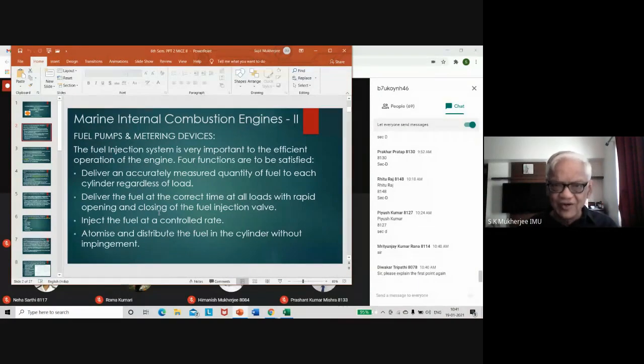Then all the units will be differently loaded. So then you will have a very unbalanced engine. Balancing of an engine is not only physical balancing, that means with balancing weights, dampers, and these things. There is also something called power balancing. Power balancing and mass balancing are two different chapters.